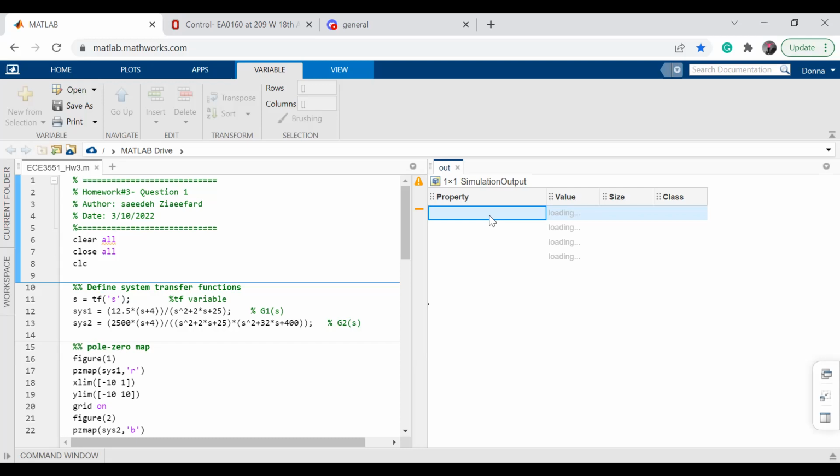You want to always check how MATLAB is transferring those data to the workspace. Previously, it would just be Y, and then you say T out and Y. Now everything is object-oriented. Basically, out is an object that has Y in it, has the simulation time, and all the other specifications of your system. So if you're using those values, check your workspace, see the structure, then use them.